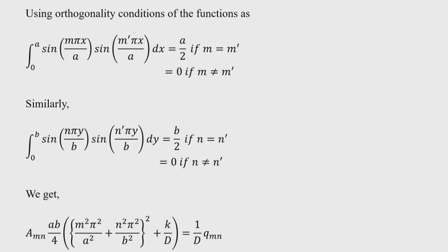So, there will be infinite terms in this series, and we have seen that for deflection only the first term is sufficient for a reasonable result, but for bending moment and shear force you have to consider more terms. However, we get the accuracy with that series, the series is a rapidly converging series.